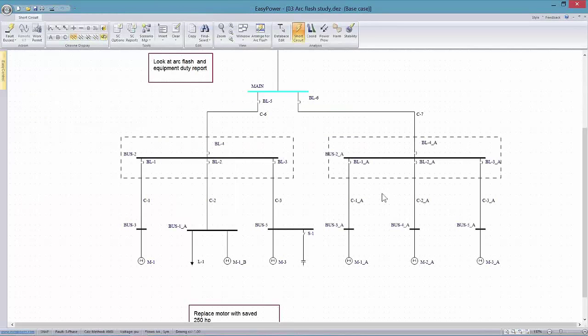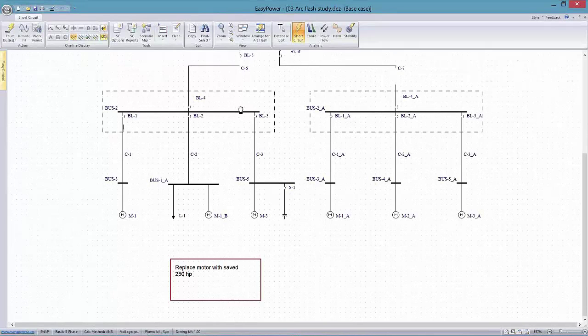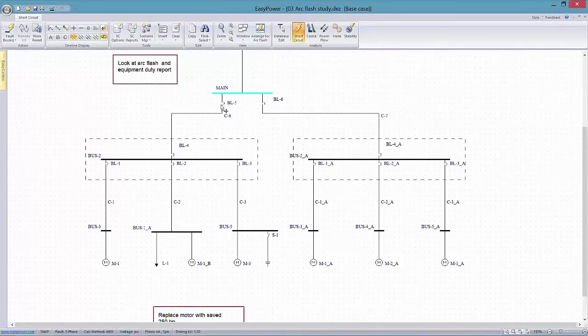What we're talking about as far as the scaling factor is what percentage of the performance of that particular motor is normal or average, and that's how we're sizing the upstream branches, and it has nothing to do with the protective devices.